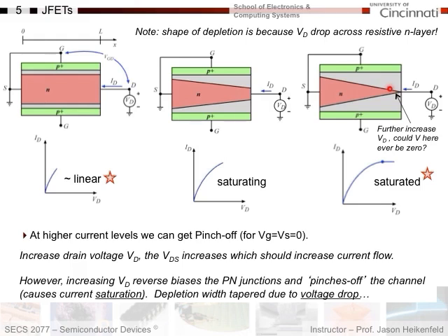So the key point is that eventually I get to a point where the channel is pinched off, hence the term pinch off. See how the channel is pinched off here? And at that point the current saturates, meaning it stays constant as I increase my drain voltage.